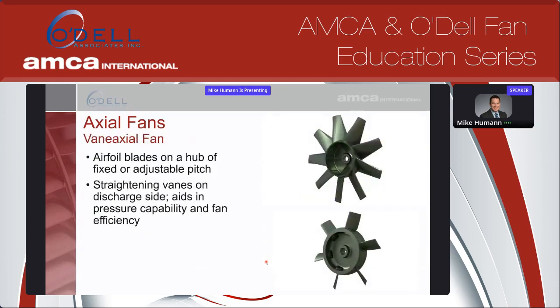The last axial fan you run into is a vane axial fan. With the vane axial fan, you actually have an airfoil blade on a hub, and that's either a fixed pitch or an adjustable pitch hub. There are straightening vanes in these fans to help in pressure capability, but also fan efficiency.